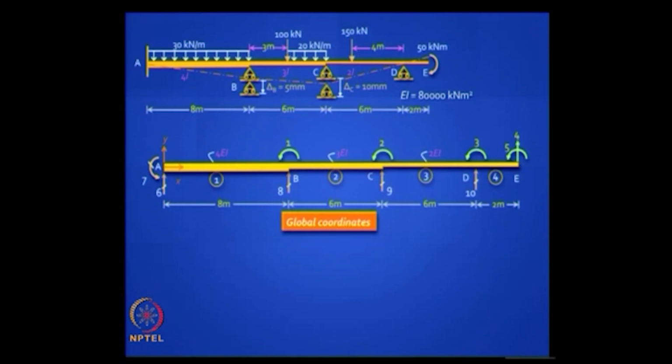The size of our stiffness matrix will be 10 by 10, KAA will be 5 by 5, and that is the one you need to invert. So it is not a problem that you can do manually, you will have to resort to using some algorithm or using MATLAB, but this is just a demonstration of how stiffness method can be used to solve any problem, any beam problem.